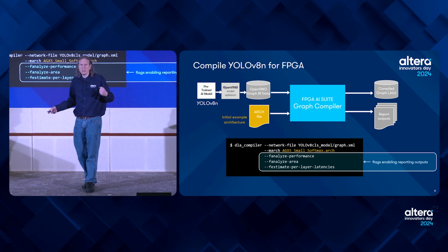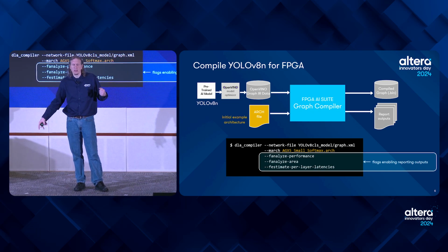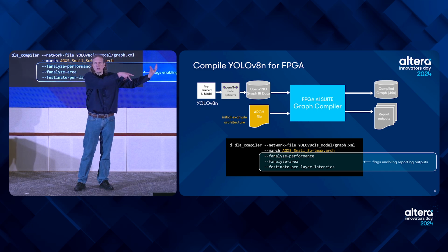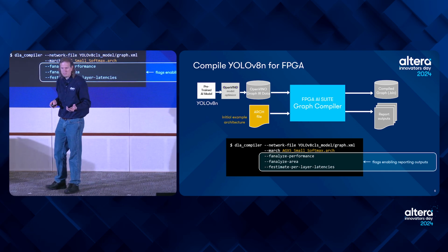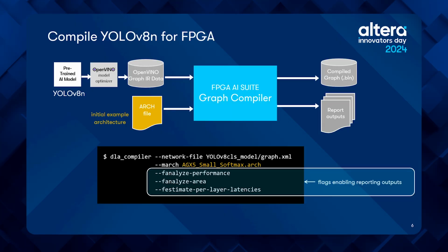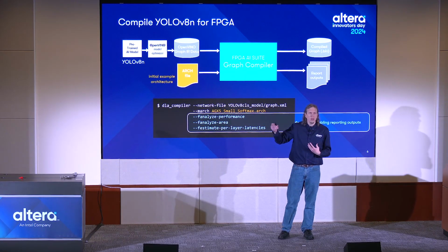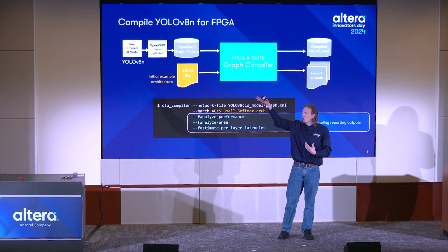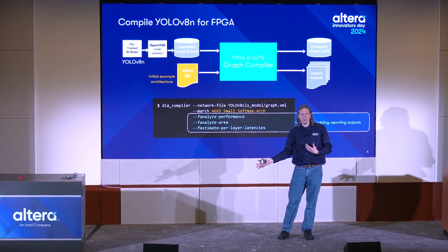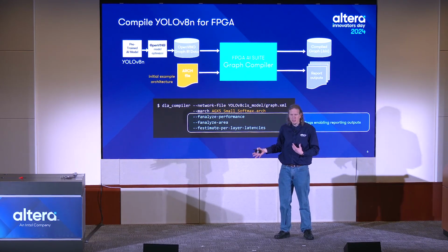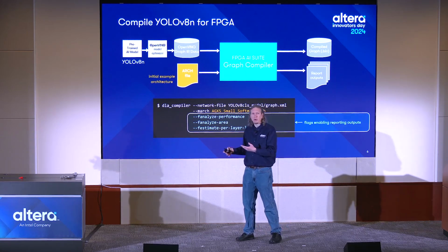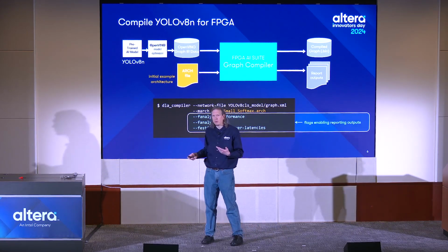If you are ready to use the instruction stream, then it can be dumped to a file and will be sent to the FPGA, which has the IP on it already. In the case shown here, however, we are asking the compiler to use the instruction stream to perform a performance analysis. This will cause the compiler to run the performance estimator tool that will go through the entire FPGA instruction stream, and for each instruction, it will estimate the associated latency. Based on this, it will come up with an overall performance or latency estimate for the graph.